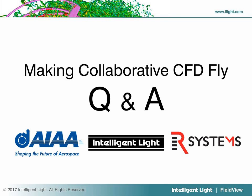Also addressing one of the earlier questions, on essentially wanting to do differences and other things like computing means and RMS of multiple solutions. I'm actually doing that with other projects within an XDB workflow where I'm doing uncertainty quantification. So I have 4 different grid resolutions, and I need to get a Richardson extrapolation. I'm doing that within FieldView. So those are lots of methodologies that you can apply to these extracts. Lots of possibilities depending on the needs of the users, right?